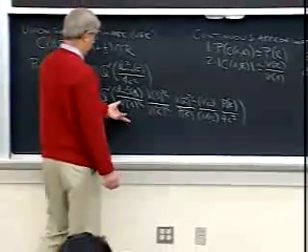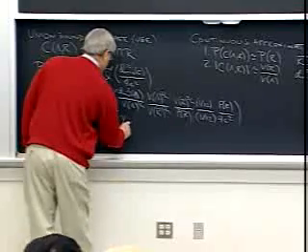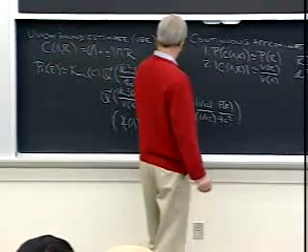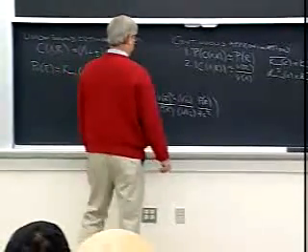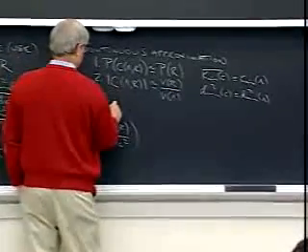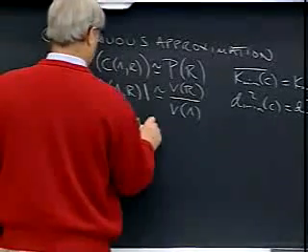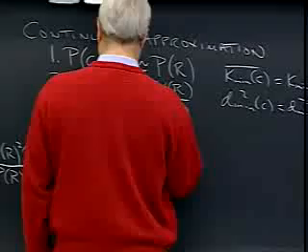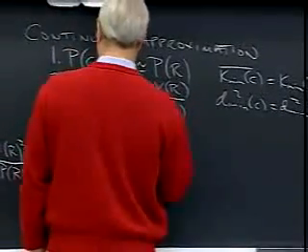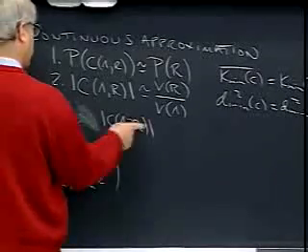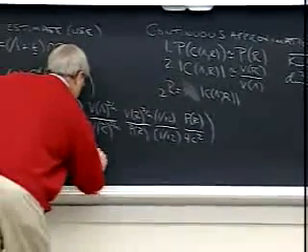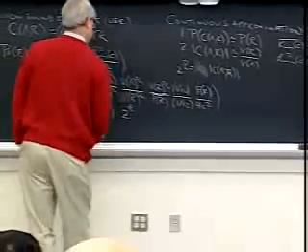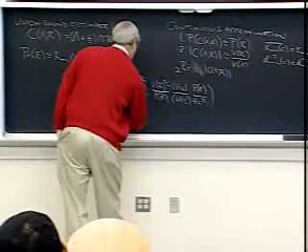Okay, so what are all these things? This is the coding gain of lambda. This, according to this, is the size of the constellation to the 2 over n, approximately. The rate of the constellation is log 2 times the size of lambda r. So the rate is equal to just log 2 of this quantity. So I can say 2 to the r equals this. So this would be 2 to the 2 over n, 2r over n. Is that right? Again, I'm unsure if that's what I want.